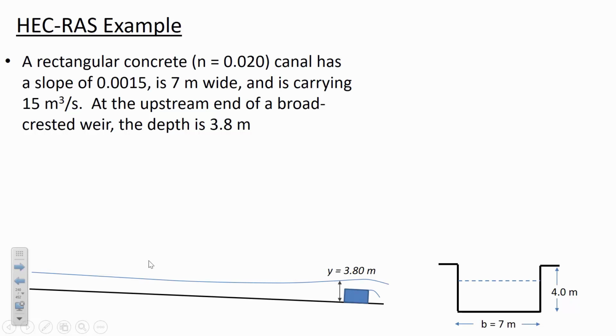Of course, the other things are going to stay the same, like the channel slope, the flow rate, the roughness. So all of that's going to stay constant. We're going to try and put that into HEC-RAS. Now, one of the tricky things in HEC-RAS is that the editor for defining what the channel geometry looks like is basically an XY coordinate system that we have to utilize.